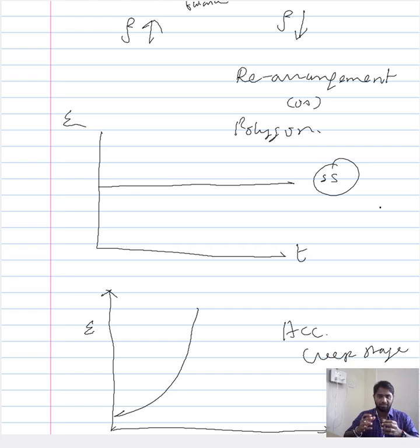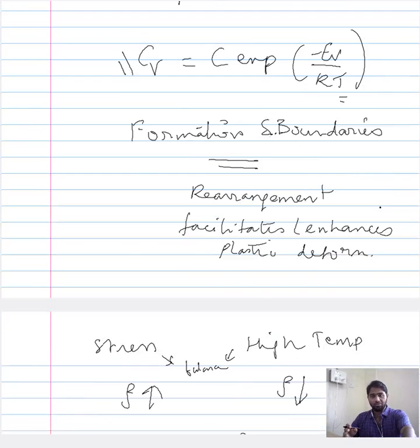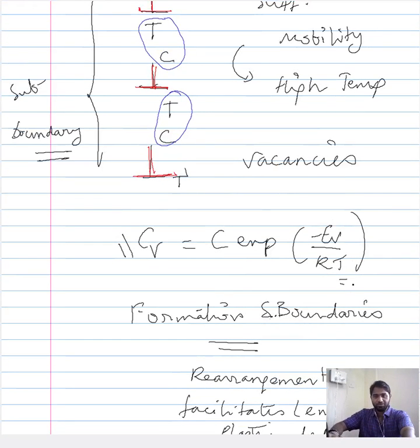Now we saw that with respect to the temperature in this expression, and also for the overall annealing rate, temperature plays a vital role. From this you can also try to conceive how an increase in temperature, or a decrease in temperature, would affect the different sections of the creep curve.